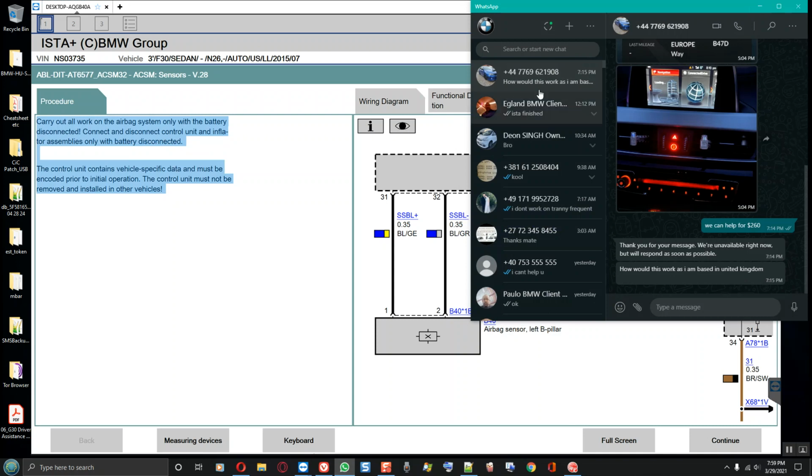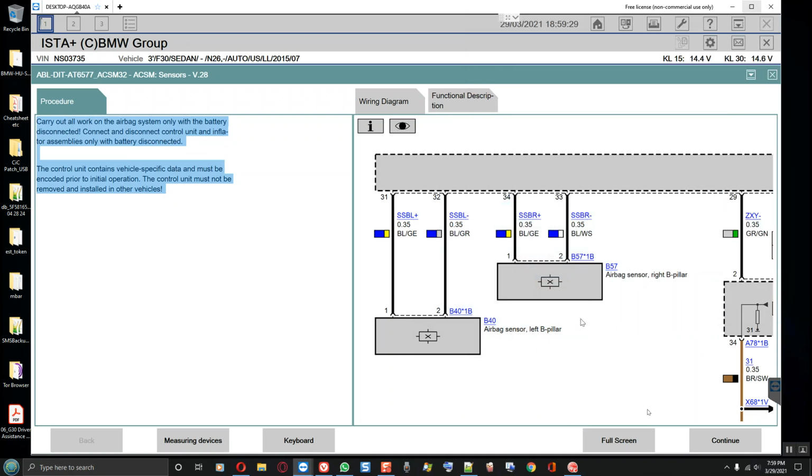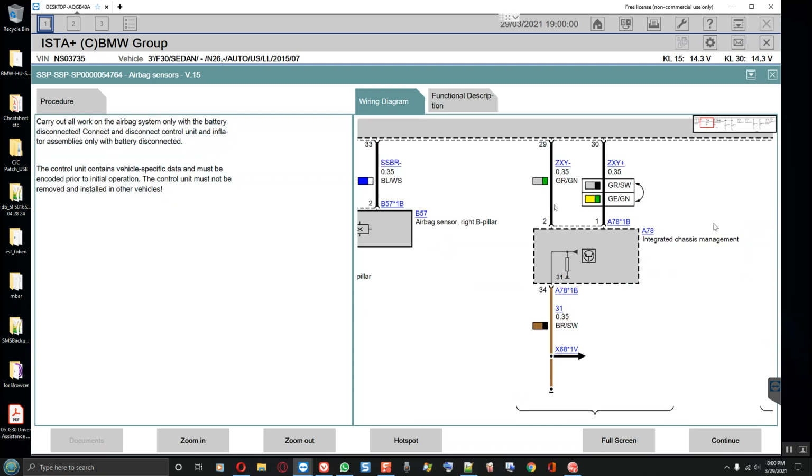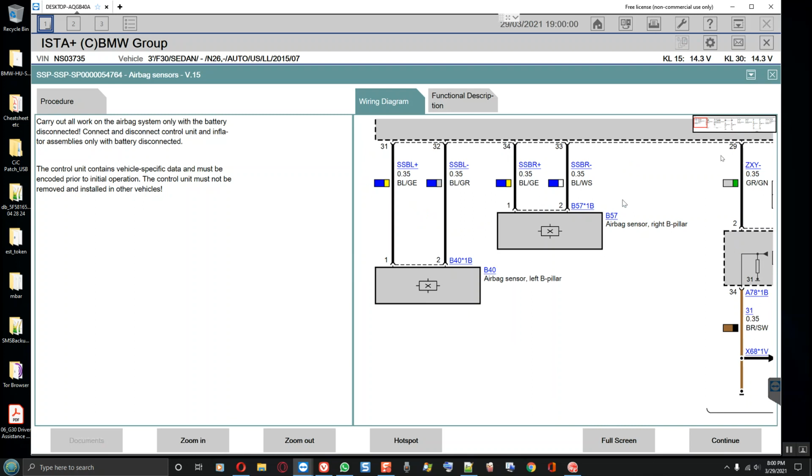Okay, cool. I just want you to remember it because some shop forgot to disconnect the battery when he pulled an airbag module out, and it's that lateral sensor inside. You moved the module, like turned it around to unplug it, and since the battery was still connected, the car thought it rolled over and it blew all the airbags on him. It was really funny. The service manager didn't think it was funny, but everybody else did. Yeah, man, you have to remember, because it sends a signal to fire the ignition circuits, because it'll think the car's rolling over.